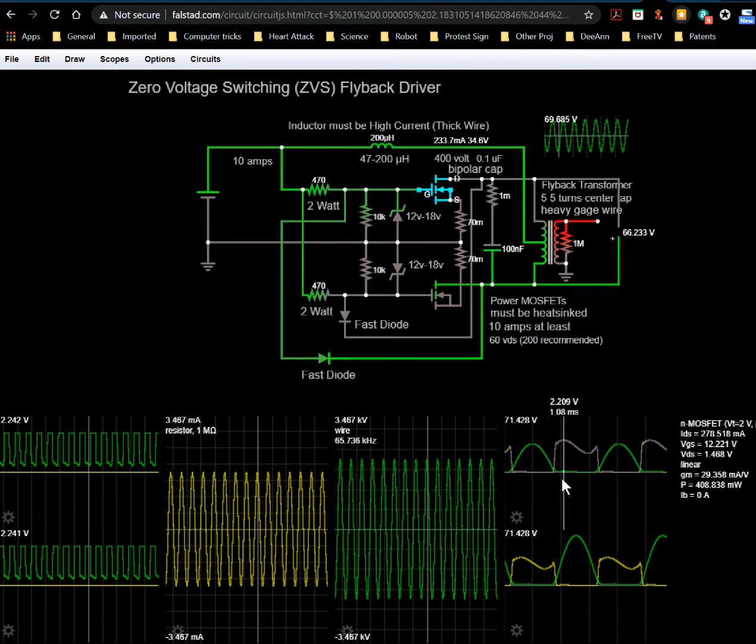Again, it wouldn't be efficient, because at a low frequency the square wave is really not doing anything most of the time. It's just drawing current through the inductor for no good reason, and it's not inducing a voltage into the secondary, because that only happens when the current is changing. In a square wave, you can end up in a situation where it's static, because the current's not changing, it's square, right? At some point, this field will be fully charged up in this inductor, and once it is, it's not going to do anything on the secondary, so you're really wasting power. But at any rate, I digress.